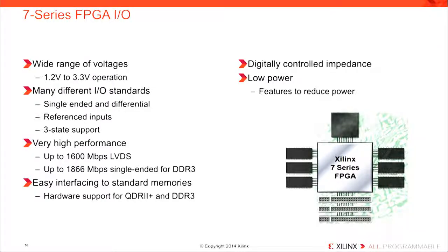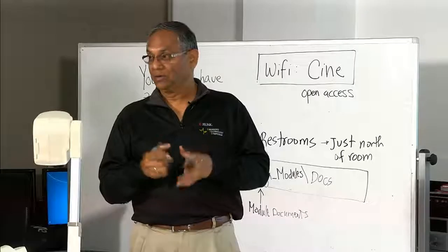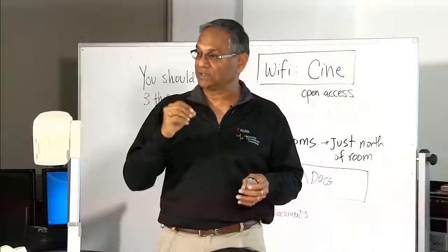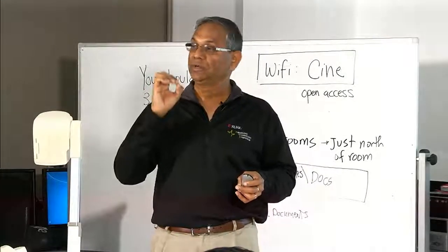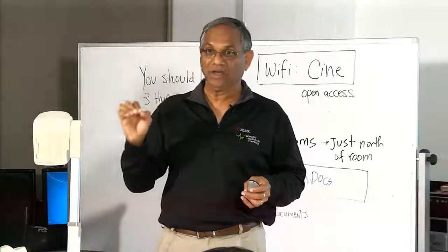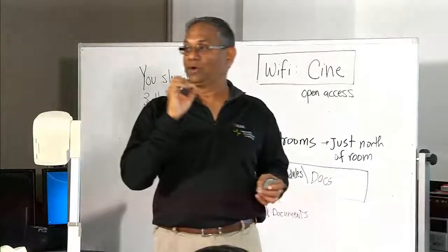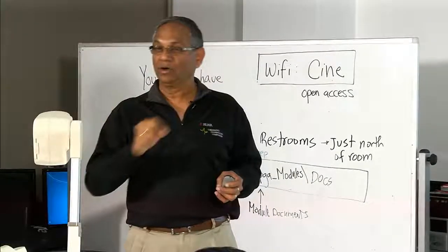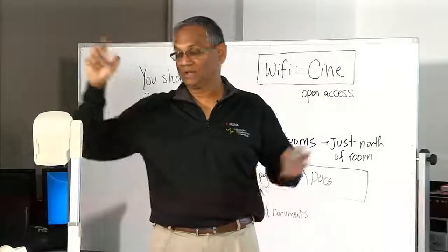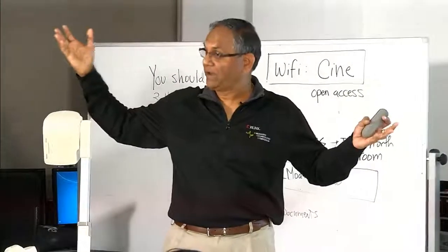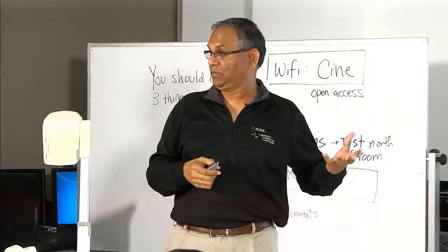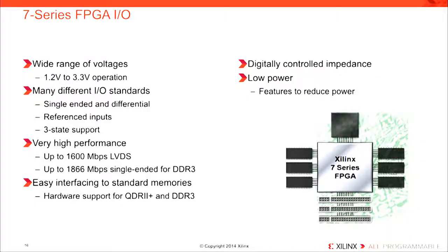So as part of the I/O planning, or as part of post synthesis configuration, or through Xilinx design constraint file, you can say I want LVCMOS 33, or I want say LVCMOS 25. You can configure them. Okay, and so you can do those for various voltages.